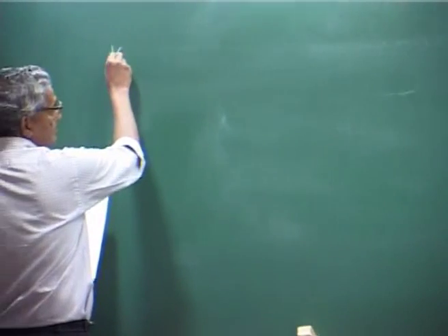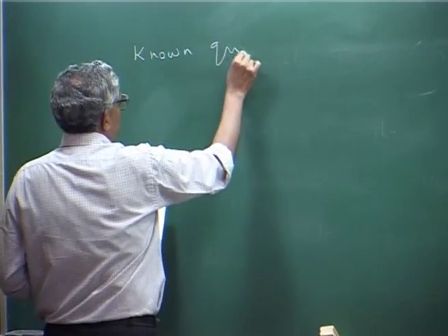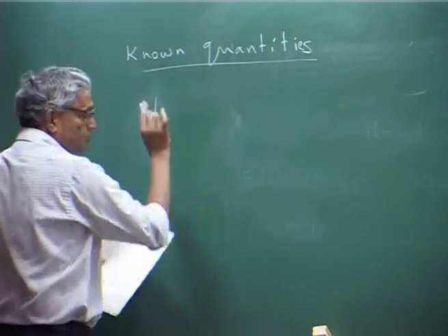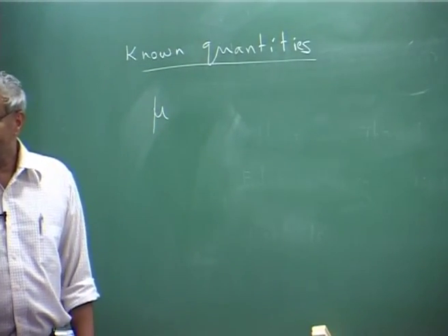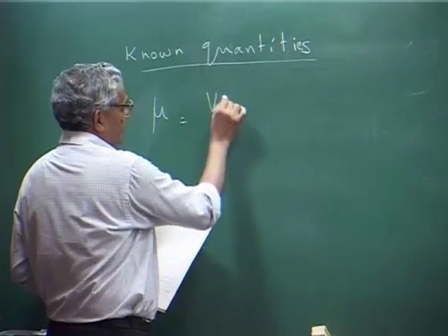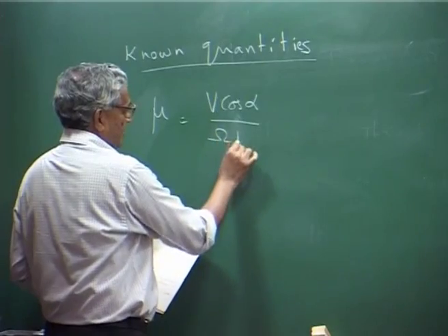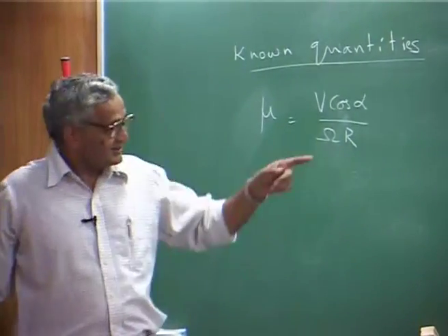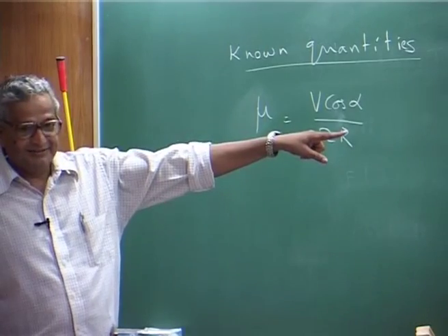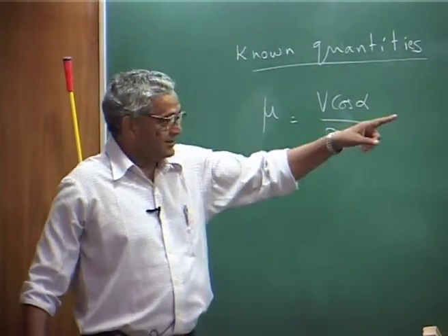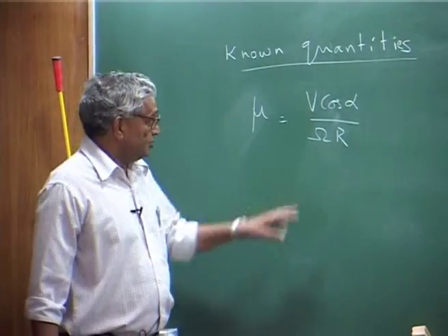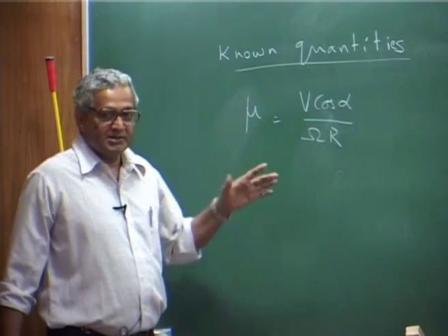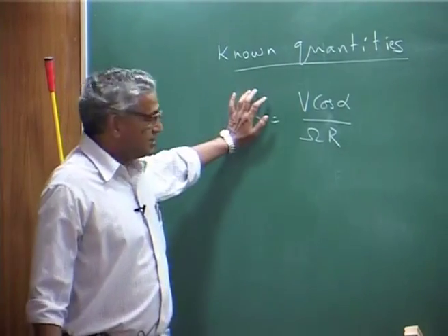Now, when we prescribe the flight condition, first we take the very simplest case. Simplest case is, I will put it, known quantities. Your mu, which is the advance ratio, this you say I know it, which is, please note this alpha is attitude of the, basically alpha is that pitch attitude, pitch theta, okay. Alpha is that. We do not know this to start with. That is why you always use advance ratio I am using. Okay. Assume that this quantity is known.